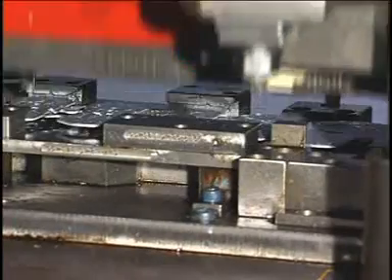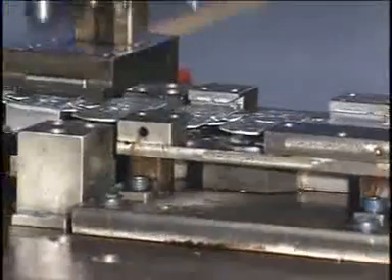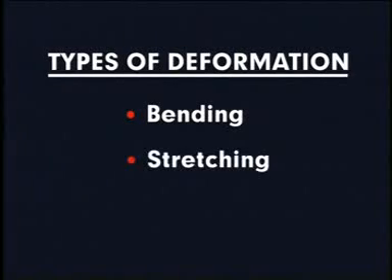The main manufacturing requirement for most sheet metal applications is good formability. This is the sheet metal's ability to deform into intricate shapes without defects in the finished part. In all sheet metal forming operations, one or more types of deformation are involved, including bending, stretching, and/or drawing. Part shape largely determines the relative severity of the sheet metal's formability, especially where drawing and stretching occur. But other factors also influence formability.